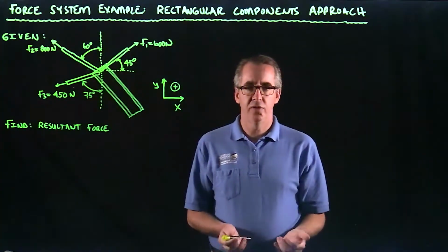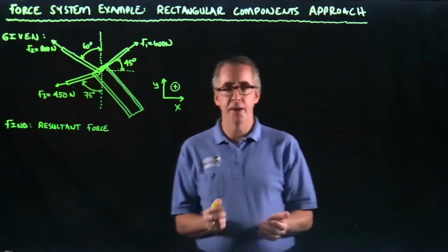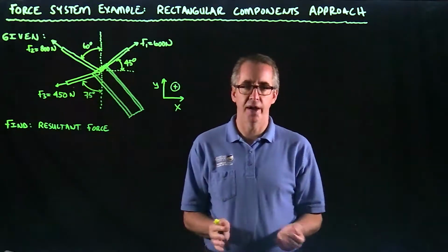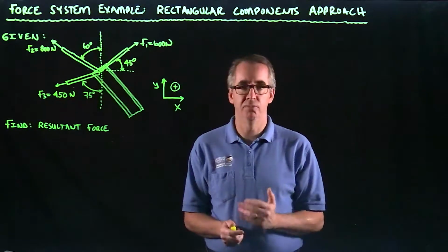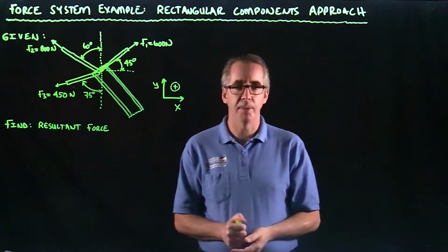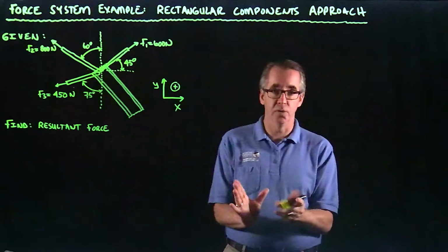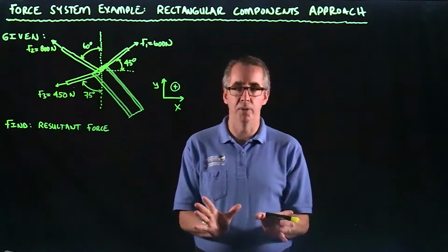Okay, in solving force systems problems, there are various approaches that we can use. Of course, we can use a trig-based approach where we use, say, law of sines, law of cosines. A real popular approach, this is one I use most of the time, is the use of rectangular components. Basically, the idea is that you take these forces and you break them down into their x and y components.